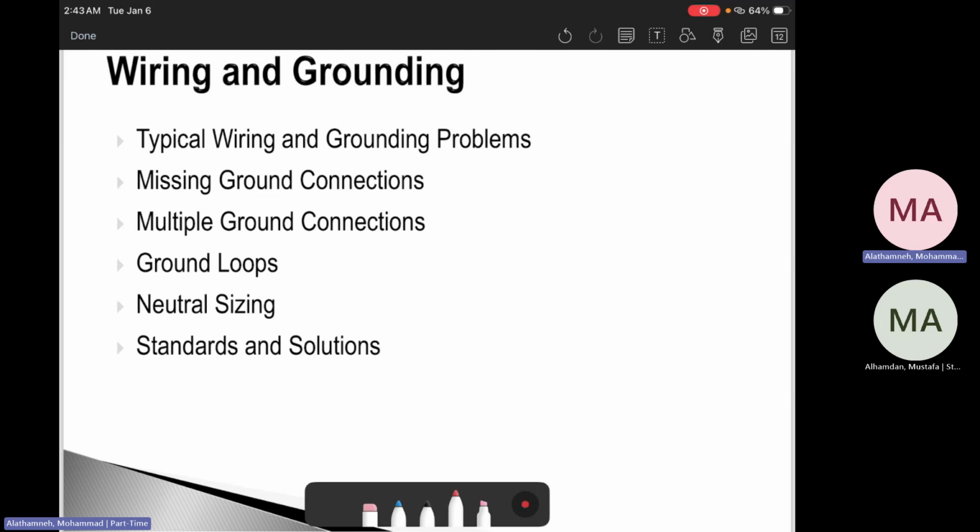Before doing that, you need to start by looking at the protection, like the earth. Is the protective earth continuous? Is the neutral bonded incorrectly somewhere? Are there multiple ground rods creating different grounds, this ground different from the other grounds? Especially when we have multiple grounds, make sure that they are all in almost the same condition. Are the communications, computers, or electronics between the equipment on different grounds, or are all of them sharing the same ground? And is the neutral heated because of harmonics? We're not talking about something academic like a case study, but a daily problem that we see in facilities, not only in Jordan but worldwide.